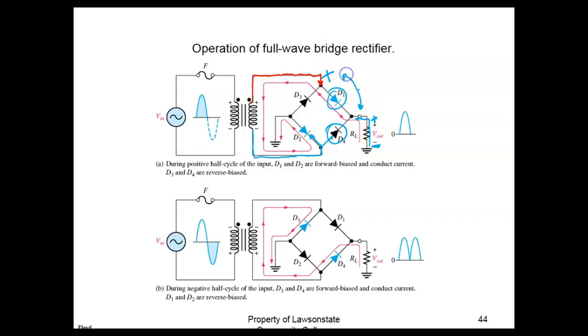And this is why I teach that when we forward bias a diode, I don't say the cathode has to be negative. If you ever see on a test that to forward bias a diode, the cathode has to be negative and the anode has to be positive, that's false. Normally, your anode is 0.7 of a volt more positive than your cathode, or your anode is 0.7 of a volt less negative than your cathode. So it's not negative in cathode, and some books kind of teach that, or they don't iterate that, and it's very, very important, because this is going to be on a test.